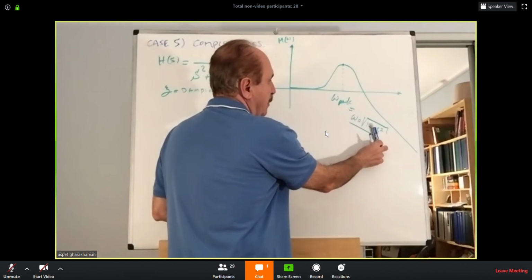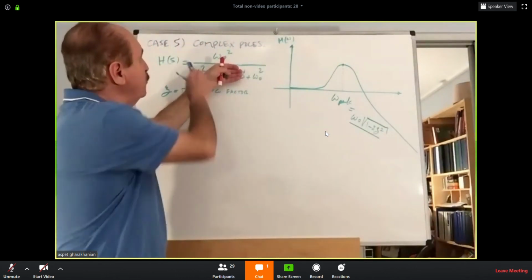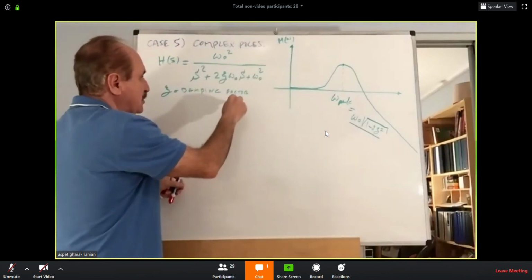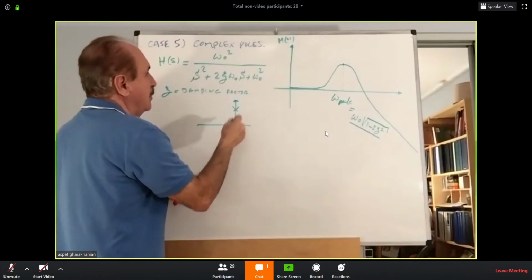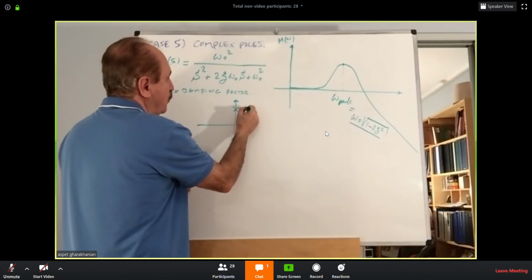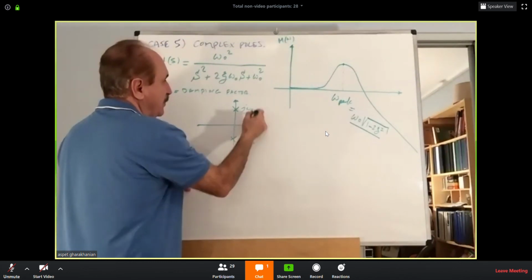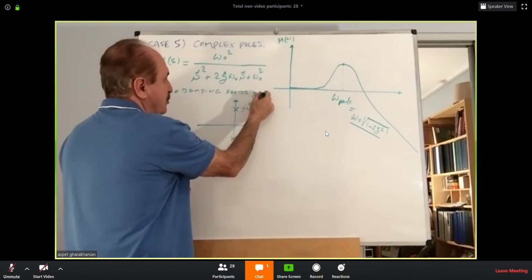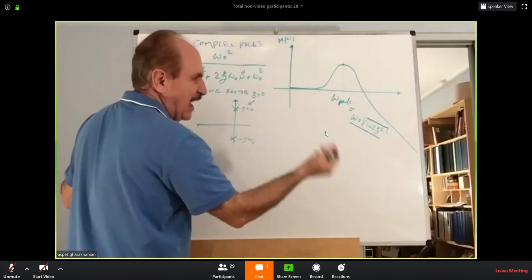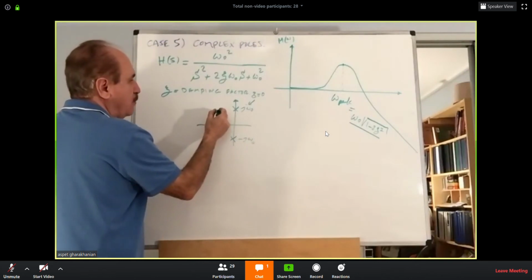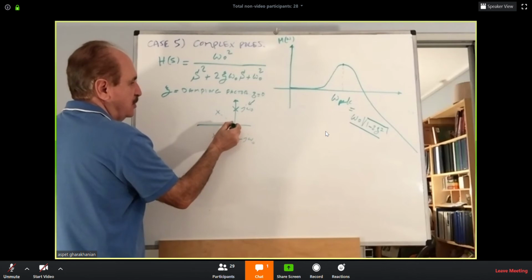See here. If you have no damping in the system, zeta 0, it means you have two complex poles placed on the j omega axis. One pole will be j omega O, the other one will be minus j omega O, and that is when zeta is equal to 0. Once zeta is somewhat positive, maybe half, the poles will move here. Then you have a damping situation.